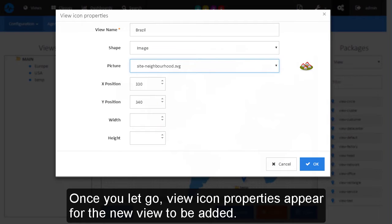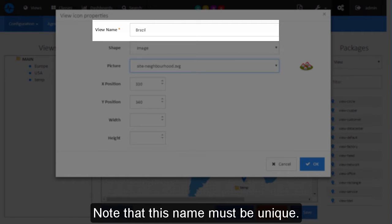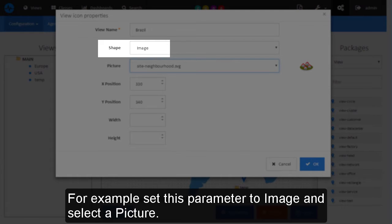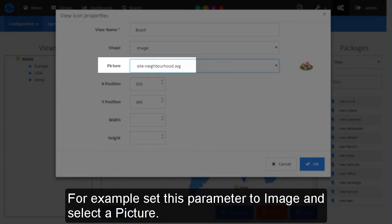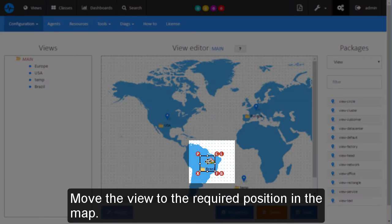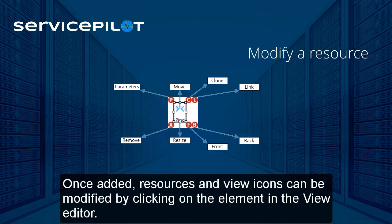Once you let go, view icon properties appear for the new view to be added. Name the view as required. Note that this name must be unique. A non-default shape can be set for the view icon. For example, set this parameter to image and select a picture. Press OK to close the dialog box. Move the view to the required position in the map. Save the changes by pressing on the Save button.